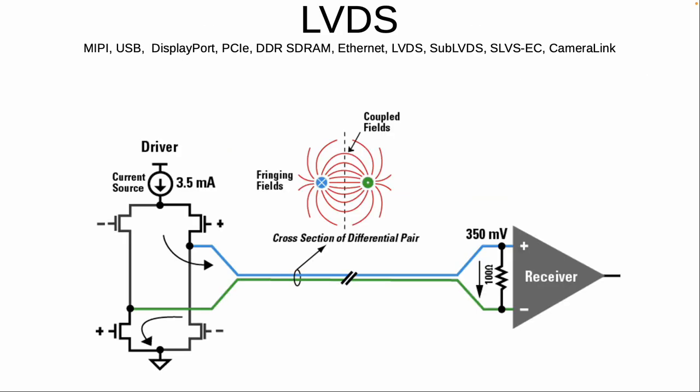The more common one is sort of the LVDS approach. And so what it does is you drive a circuit, and at the receiver it's got maybe a 100 ohm resistor, and so there's some voltage across that, and so that generates a signal. And what you do is you just change the direction of the current when you want it, as a way of sending a signal, and that way the total current flow is constant. It just changes directions in this segment of the wire, and so that makes the work easier for the voltage supplies.